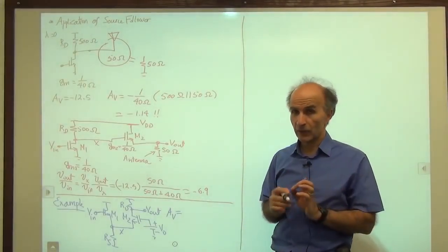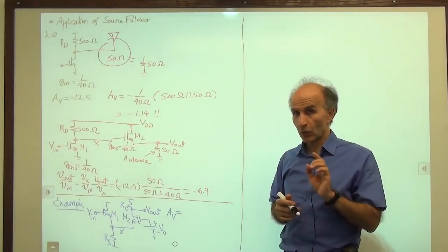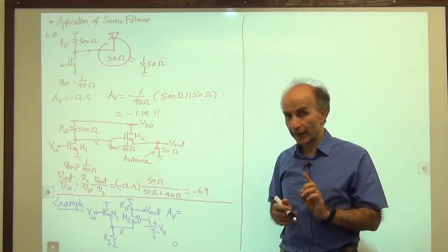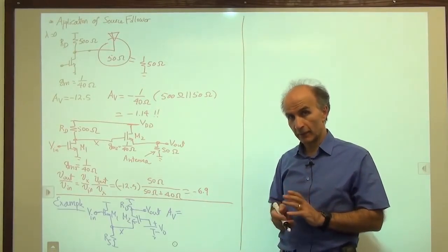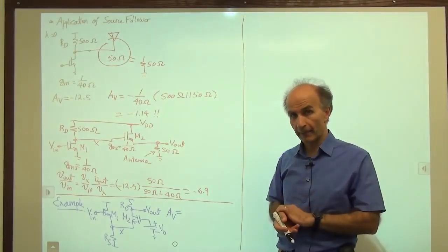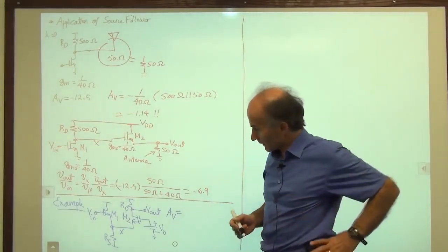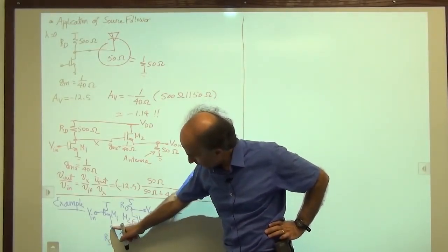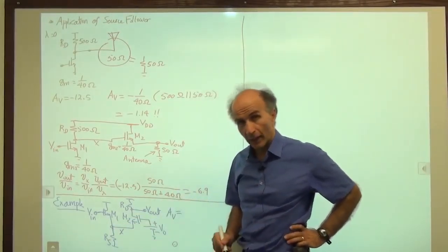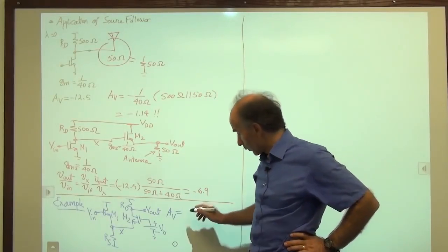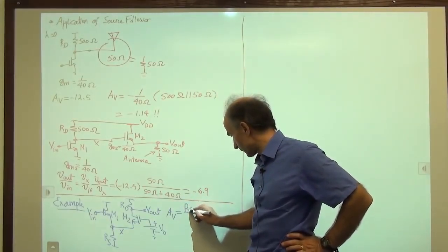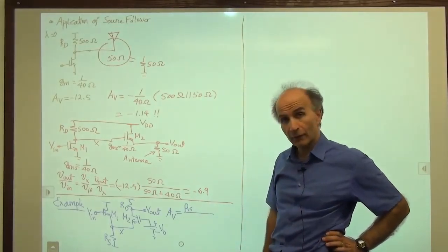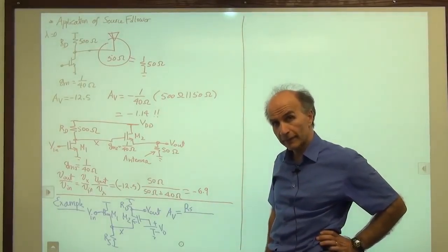And we said that the voltage gain is given by the total resistance tied between the source and AC ground divided by that plus 1 over Gm. So how much is the total resistance tied between the source and AC ground? Okay, well, we have RS going to ground, so we keep that. Do we have anything else going from X to AC ground?